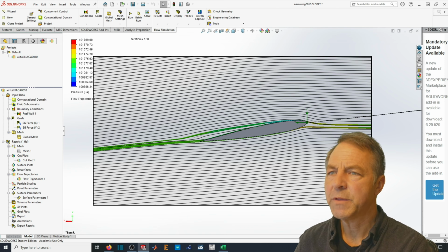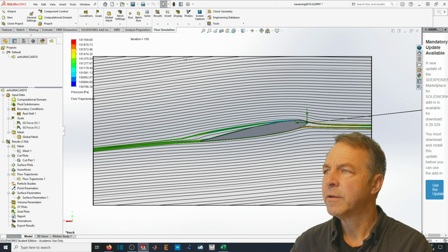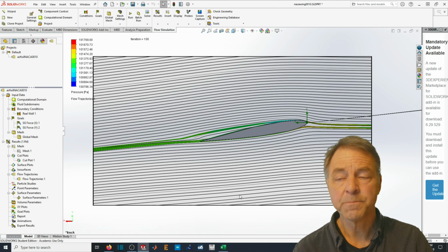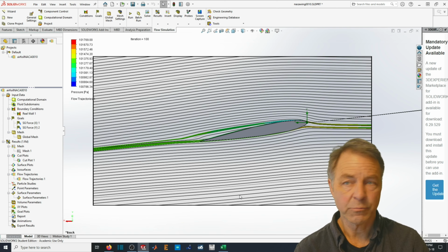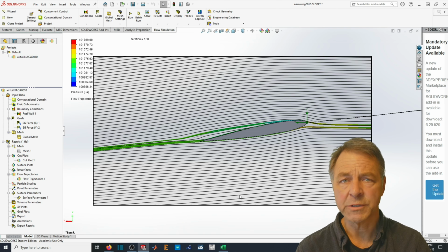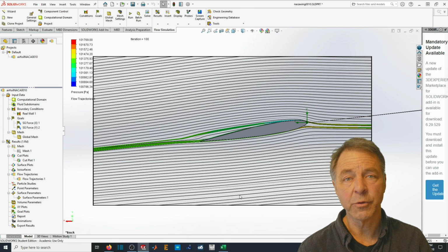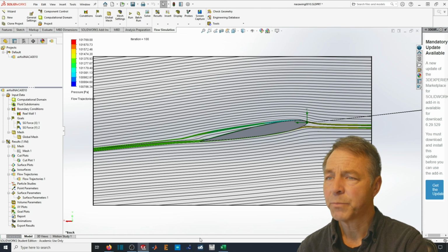And so you can see from this that my model domain up here, there's still something going on up at the top of this domain. And there's still something going on down here. Well, the fact that that domain is so small produces an error in the result because the simulation isn't really knowing what happens outside of those boundaries. So that creates a problem when you try and calculate some fairly derived numbers like the force on something like this. So that's a problem.